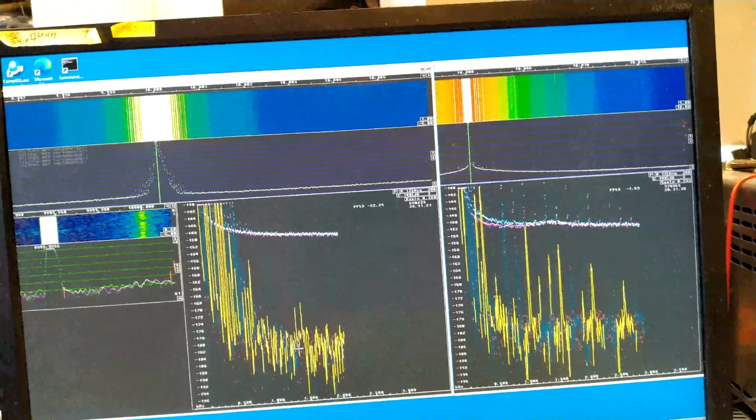And with the M audio at this 6 minutes, 6.5 actually, and 15 kilohertz, I see minus 176. That reflects the lower dynamic range of the sound card system at 15 kilohertz.